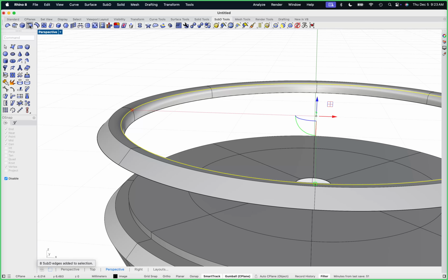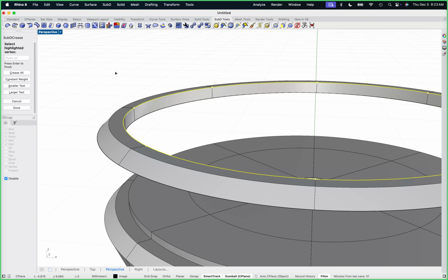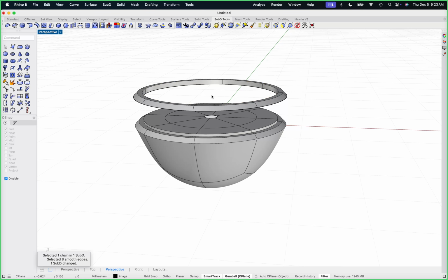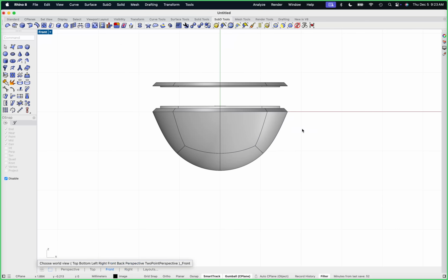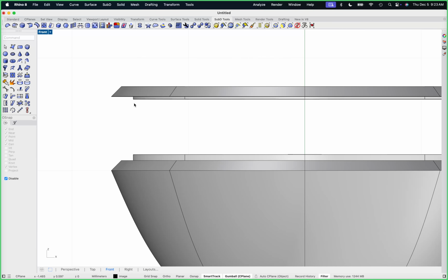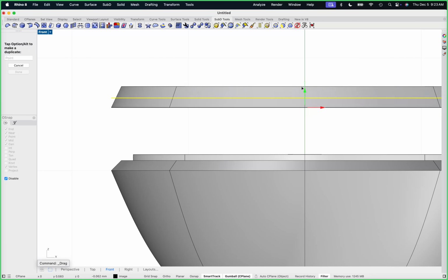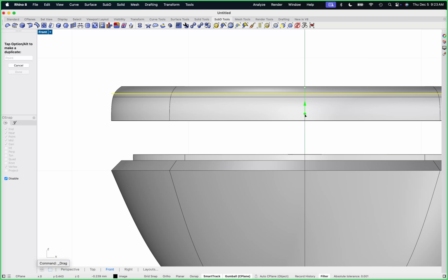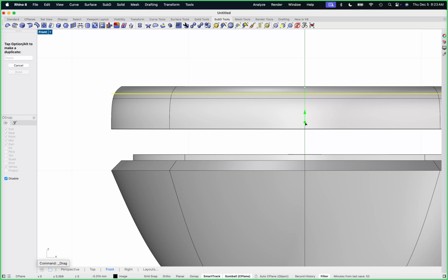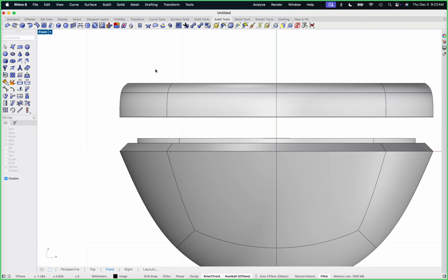And I'm creasing edges just to kind of give myself some constraints, right? Just so I kind of know where I'm going and what I'm doing and all that kind of stuff. I may change those later. And so let's double click this edge, shift control, double click this edge. Let's scale those both to 0, which is going to align them. And then we can decide, like, you know, how much of that we get. And then I'm going to pull the ring off of that thing like that.